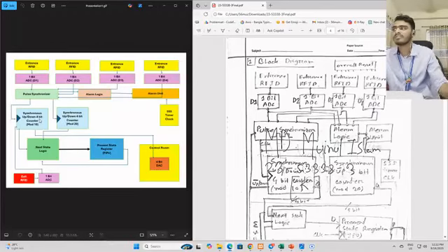So if some passenger exits through this RFID, which is also connected with a 1-bit ADC, this counter goes downwards, and if it gets a hit from these entrances, it goes upward. So this is an up and down synchronous counter, and this is a mod 10 counter because one of our requirements is that only 10 passengers are allowed on the platform at a time.